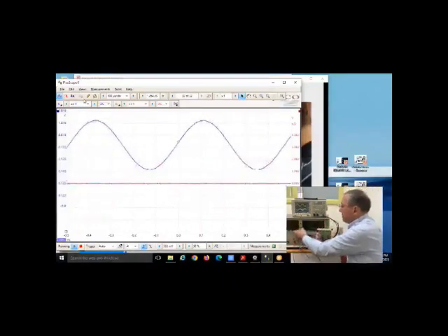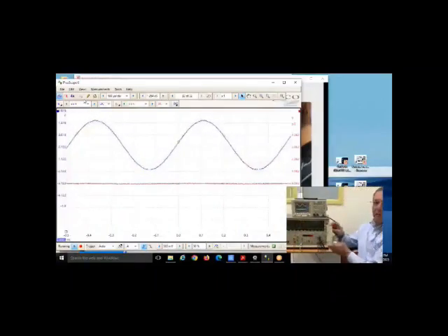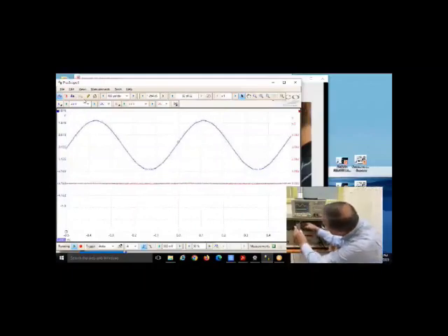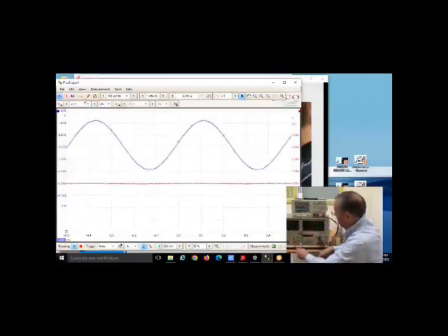So let me, for simplicity, take out the adder and I'll plug in this multiplier. You see the multiplier has 2 inputs and 1 output. And here this switch is coupling, where the inputs are either AC coupled or DC coupled. So I'll plug this in. So what I'll connect is 2 kilohertz to 1 input.